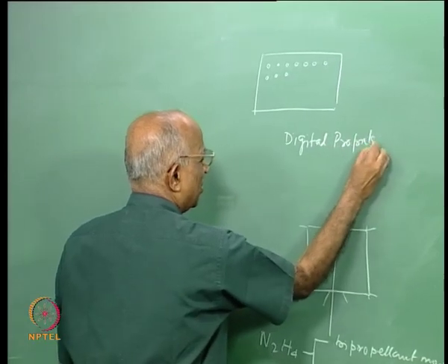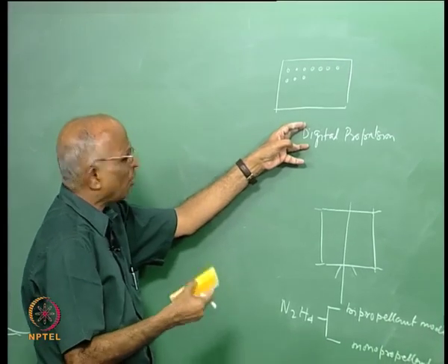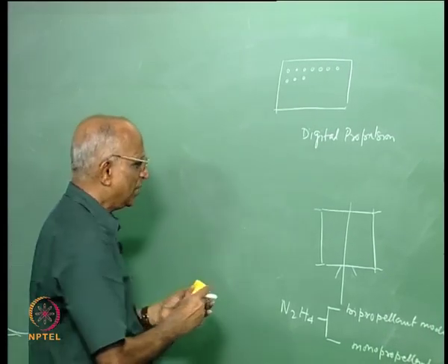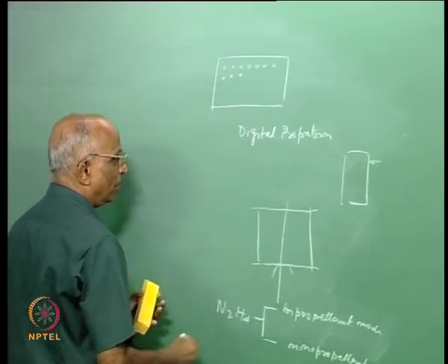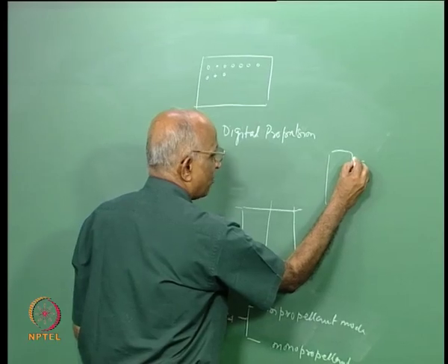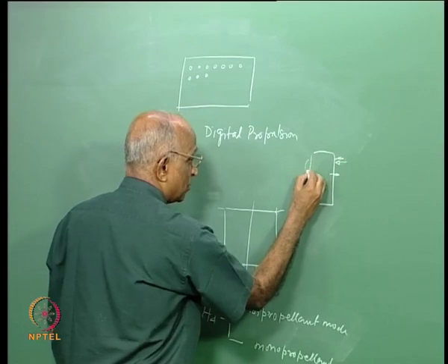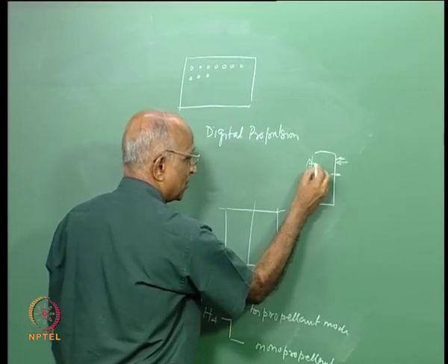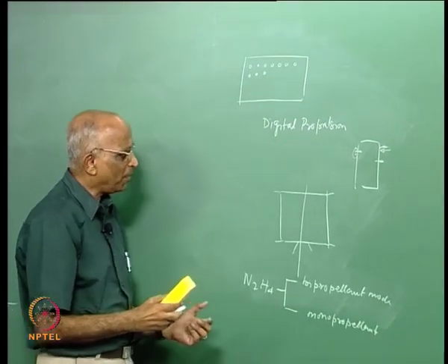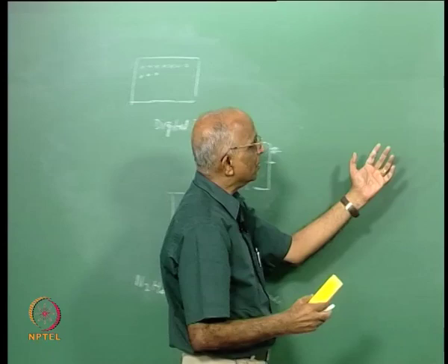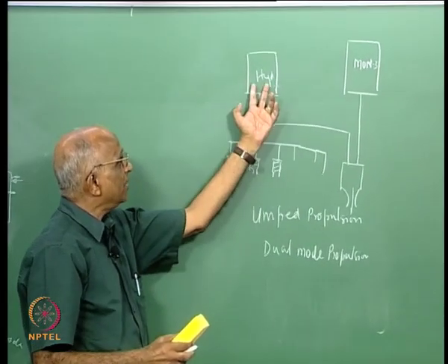As you see, the subject of propulsion, especially rocket propulsion, is something in which a lot of developments can take place. All I want is for a spacecraft to be given some small force like this, it is in vacuum. Therefore, I have a pellet here which I fire and it gives me this. If I want a push in this direction, maybe I put some pellets over here, I fire it in this direction. Therefore, you have something like digits which you fire, and it is known as digital propulsion.